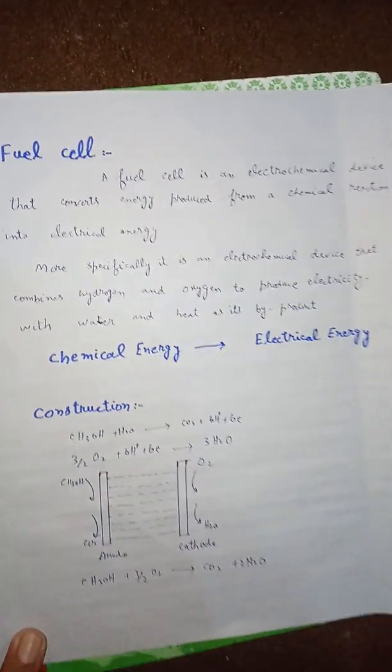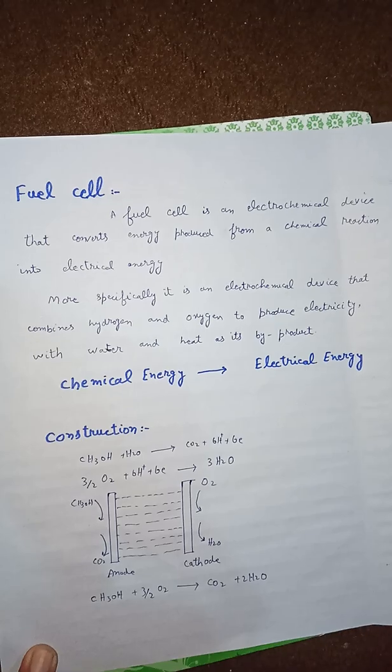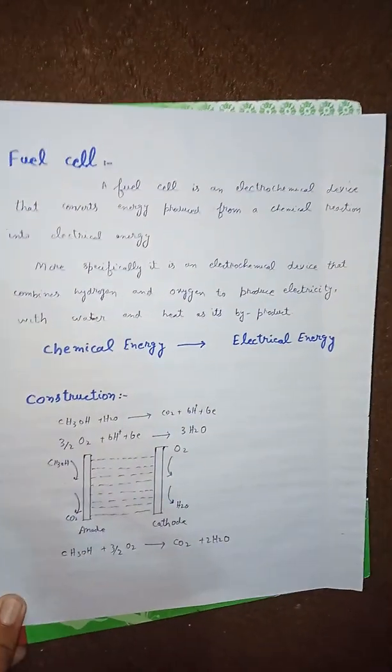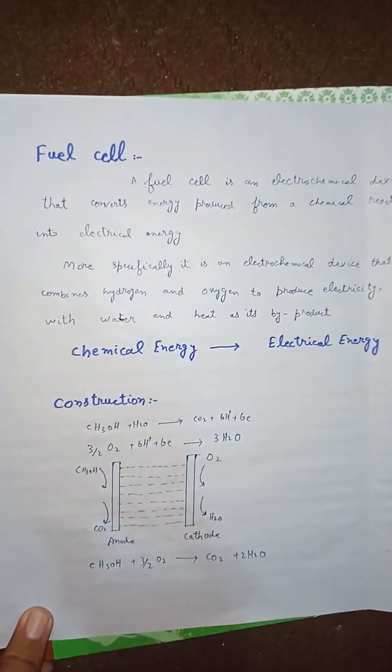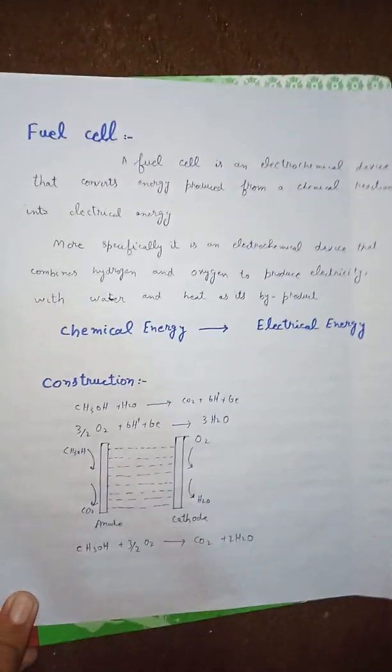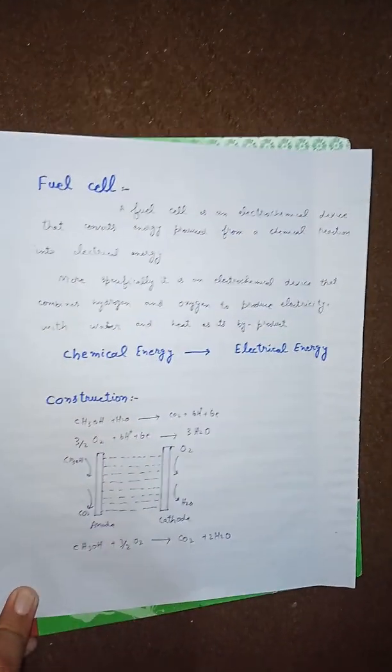Second one is the cathode. The positive post of the fuel cell. Etched channels distribute oxygen to the surface of the catalyst. It conducts electrons back from the external circuit to the catalyst, which recombine with the hydrogen ions and oxygen to form water.